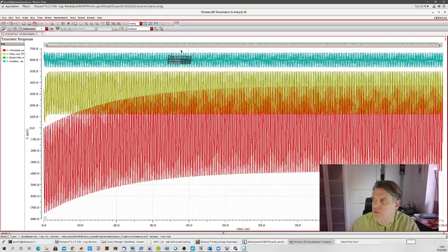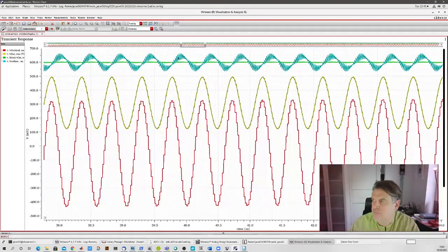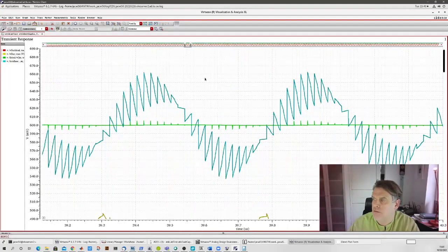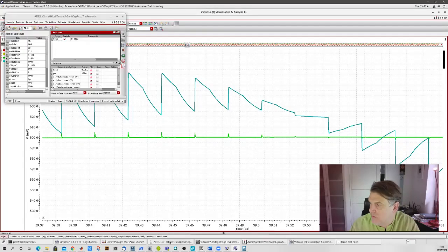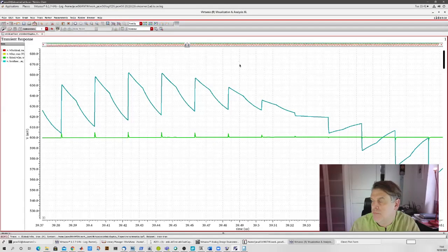Okay, and then you see the issue that we discussed today in the intro session. Ideally, if this were an op amp with infinite gain, there would be just a straight line at 600 millivolts. In our case, the ideal one also has some flaws. It's not perfectly infinite gain. I think the gain is something like 1,000. In fact, we could actually look at that. The gain is, well, yeah, exactly 1,000.